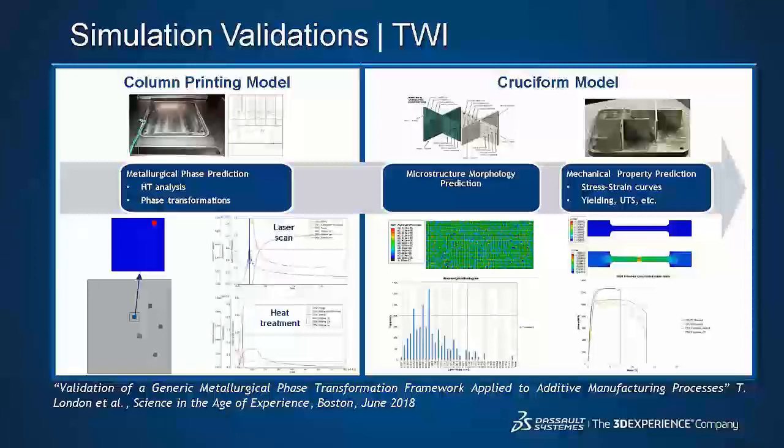These are used to connect with macroscopic mechanical properties such as Young's modulus and yield stress, also ultimate tensile stresses, etc. We have adopted existing empirical plasticity models to connect yield strength, strain, ultimate strength, and ductility limits to volume fraction content and grain size information.